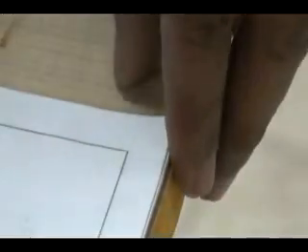So you keep your flat portion of the clip on the top. Okay, remove the clip and you keep the flat portion over the top, right? So if you have a drawing sheet, empty drawing sheet, use it as a backup sheet today, right? So exactly the drawing sheet has to match with the periphery of the drawing table, and the drawing sheet should be filled with the title block and layout. Okay, that is, you have to draw it separately.